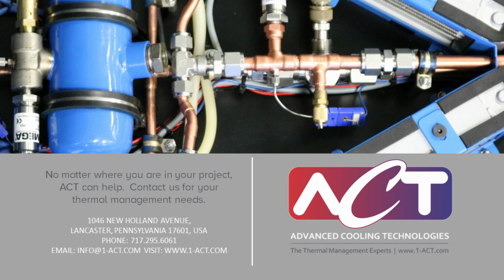All right, that's a fairly loaded question. First and foremost, in the microgravity environment, I would say they perform well, and that's mainly because typical wicked heat pipes don't rely on a gravity head to operate. They rely on the capillary pressure that's being generated by that wick structure. So all the physics inside of it are driven by various pressure drops throughout the system, your liquid and vapor pressure drops, and then overall your capillary pressure drop. So they perform very well. It's comparable to doing basically a horizontal ground test where you take most of the gravity head away from the situation.